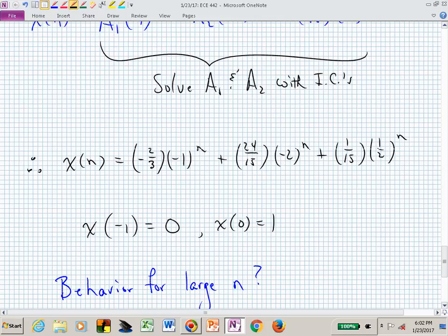So I prefer, if we're talking settling time, you have to be exclusively inside the unit circle, not on the unit circle itself. If you wanted to create an oscillator, then you would build a system that had roots on the imaginary axis, or on the unit circle. I said imaginary axis, then I'm in the S plane, aren't I? That's where you have an oscillator in continuous time. Here in discrete time, to have an oscillator, we would want our poles to be on the unit circle.